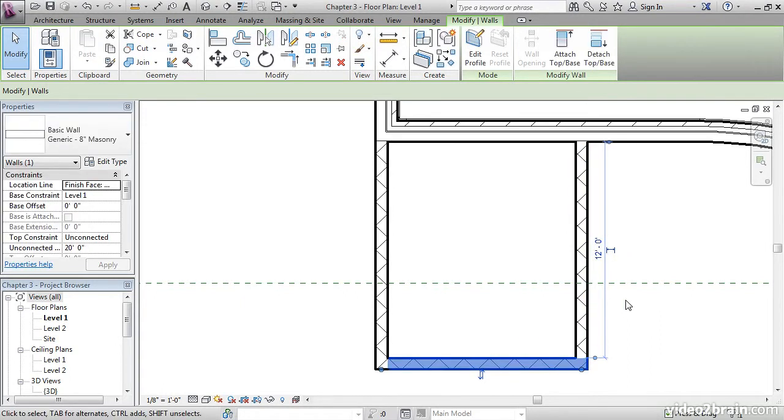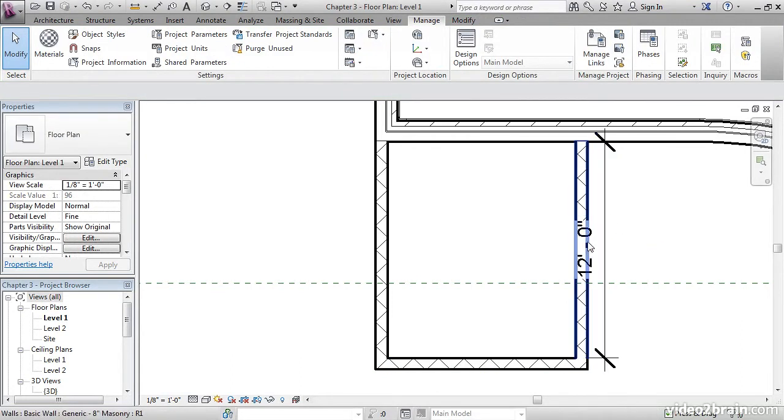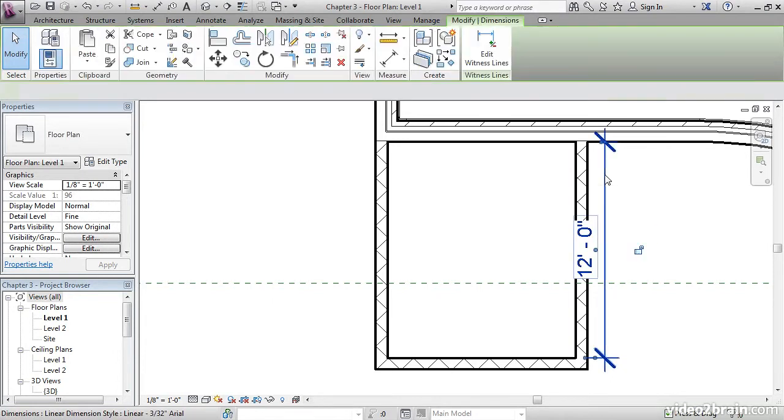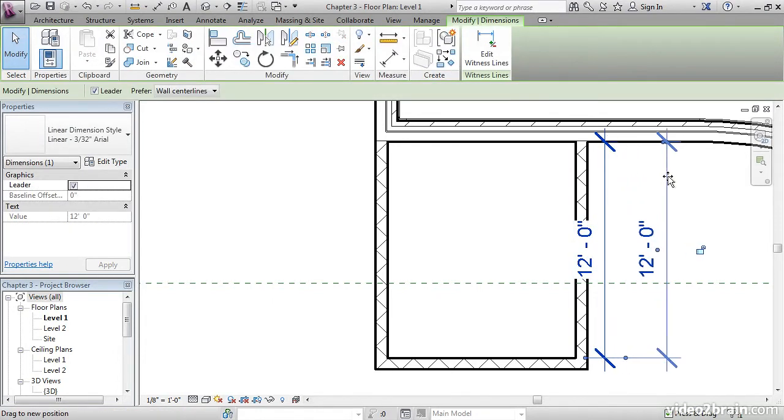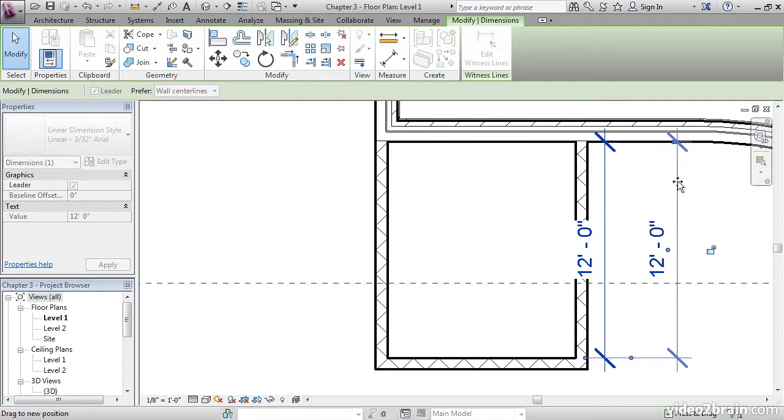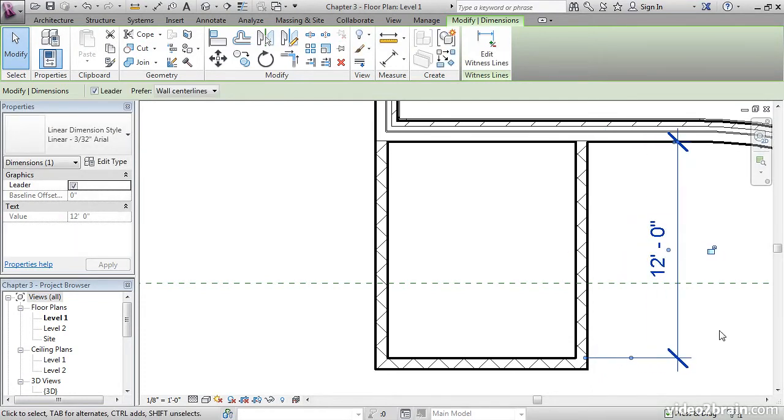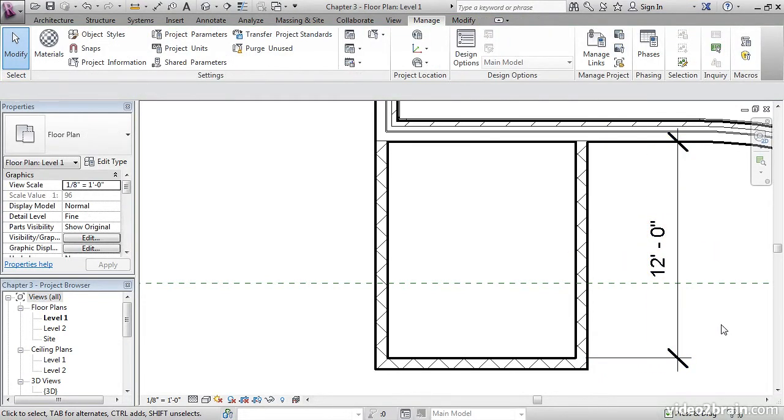One really cool thing about Revit is, once you see this temporary dimension light up, you see this little dimension icon. That's called Make This Temporary Dimension Permanent. Go ahead and click that icon and click off of the wall. You'll see 12 feet in there as a permanent dimension now. If I hover over this and select it, I can actually physically hold down my Move button and move it out from the wall. Hit Escape a couple times to clear out of any command.